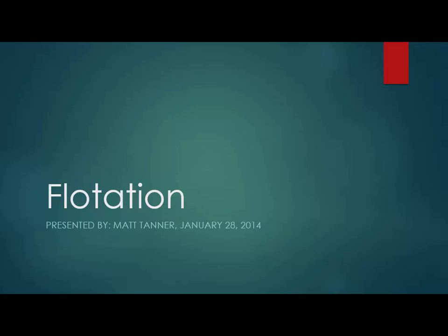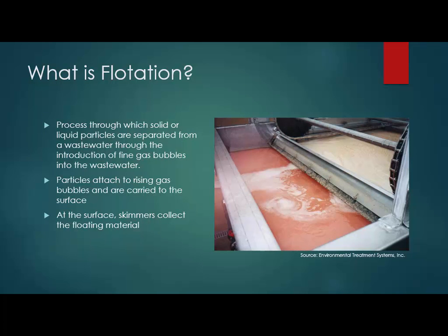Hi, I'm Matt Tanner. I am going to be talking about flotation. Now, what is flotation? Flotation is a treatment process that's used to remove solid or liquid particles from a wastewater using the introduction of tiny gas bubbles into the wastewater. As the gas bubbles rise to the surface, they attach to the particles and carry them with them, or they increase the buoyancy of the particles and carry them to the surface.